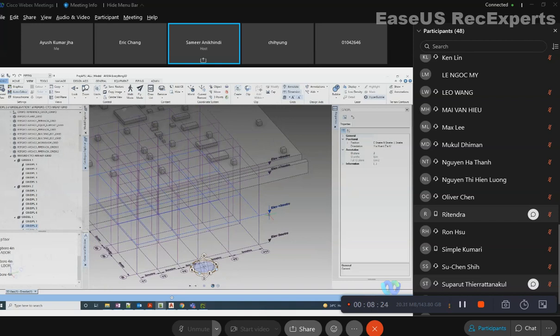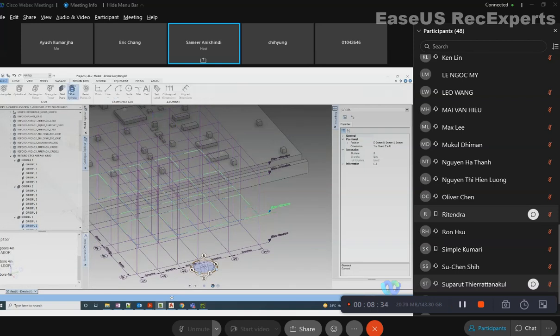If you want to add any grid plane between these two elevations, select the elevation where you want to add the grid plane. Select this and then go to design aids, grid plane. This is available only inside the grid plane modification mode. If you come out by pressing escape, this button will not be active. So click grid plane. See, whichever you have selected.